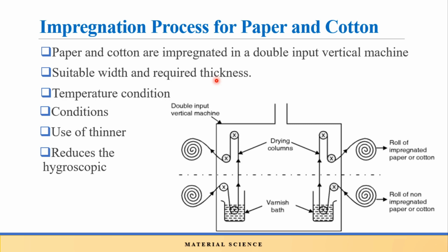By the process of impregnation, air pockets are filled with varnishes, making them electrically strong and producing uniform electric field intensity in the material. If I do the impregnation process, all the voids or gaps present on that paper will get covered, and the mechanical strength as well as electrical capacity of that fibrous insulating material will improve. So these are some advantages of impregnation.